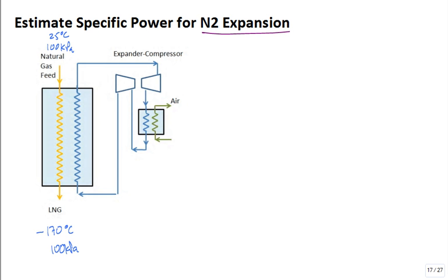All right. This is a turbine. This is a compressor. So the nitrogen gas goes in a loop. The nitrogen goes through the compressor. Then it goes to a heat exchanger. What's it doing with the heat exchanger? It's dumping heat to the atmospheric air. Okay? And then once it's cooled off after the compressor and the heat exchanger, it goes through the turbine. What's going to happen to it? It's high pressure coming into the turbine, but it's going to expand. Now it's really cold. See, that's the gas refrigeration cycle.